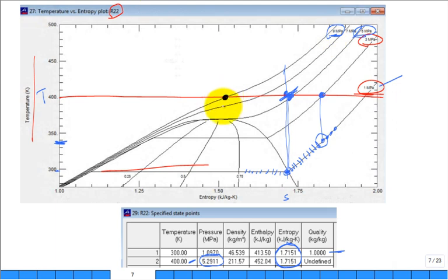Is that going to be good for the system? No. Because if you expand it, you're going to be trying to expand a thick, soupy, two-phase mixture for the majority of the time right in here. It's not good for turbines. It's not going to work. So in this case, no, we need to sort of stop it. We need to have it only up to about 5.3 megapascal.